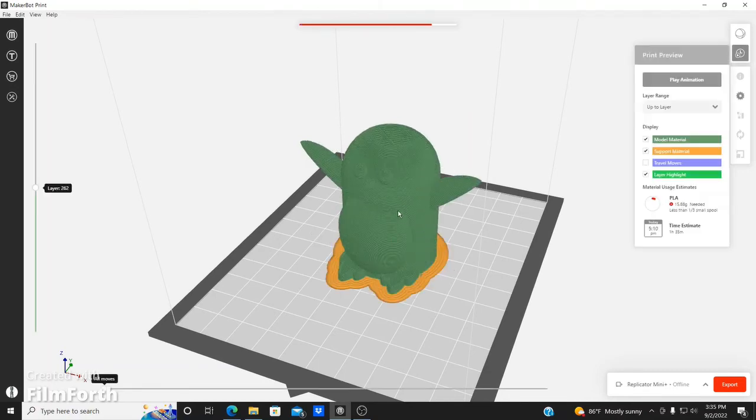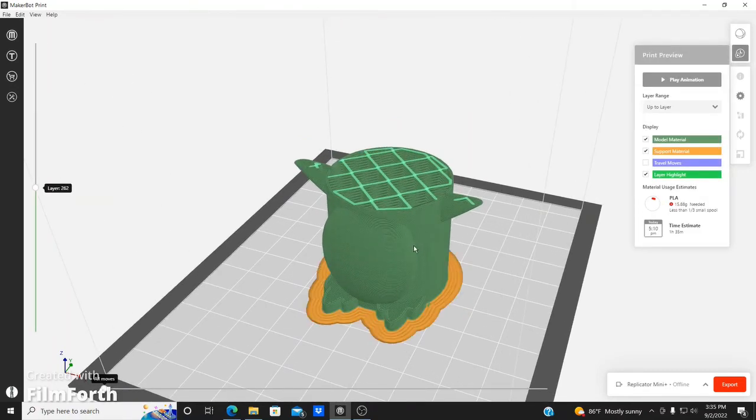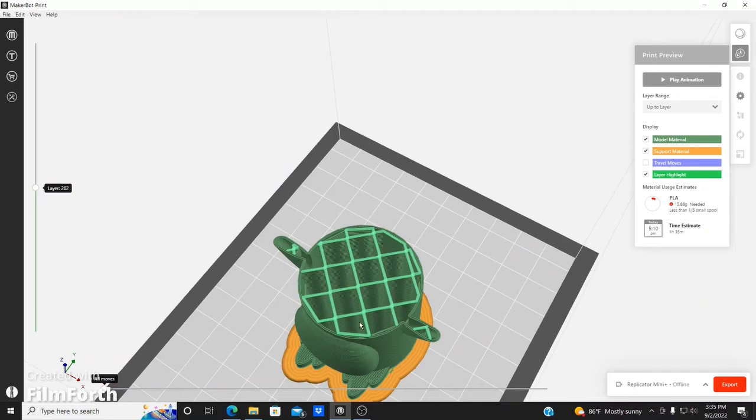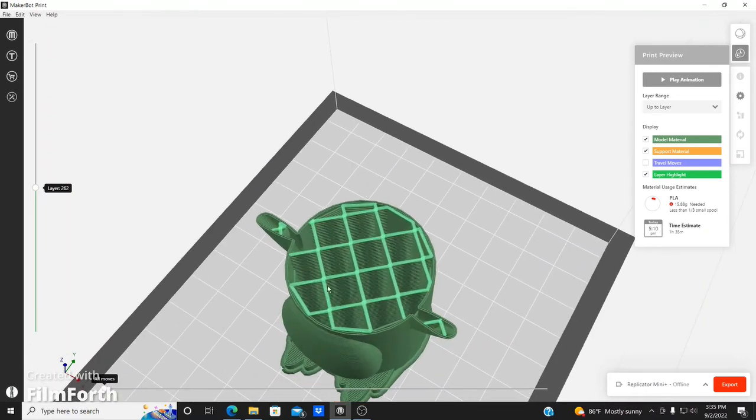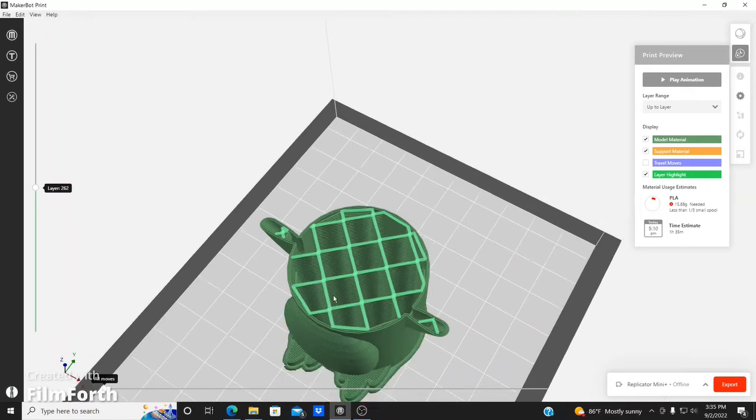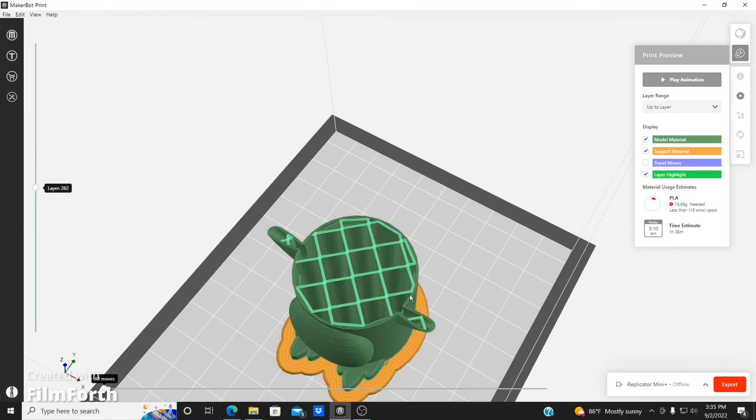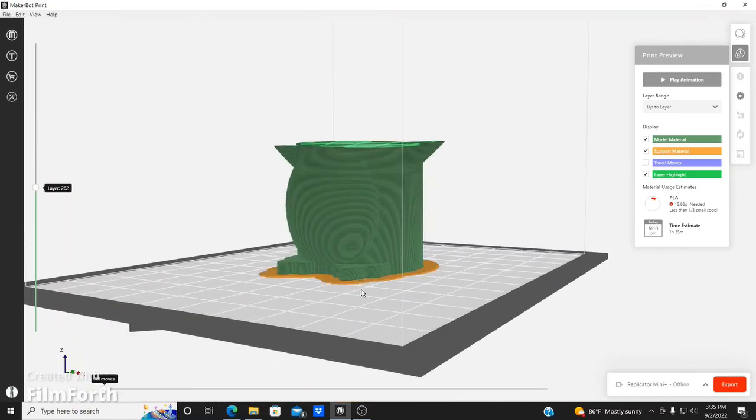Okay, and there he is. Look at the inside, this is what it looks like from the inside. This is what 10% looks like, with the diamond shape or the squares, and that way it creates less material. On this side, you notice it was at 18 grams, I believe, but now it went down to 15 grams, because this is the most important one as well on the PLA, which I'll discuss after this one, the raft.